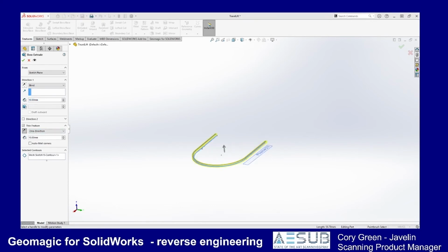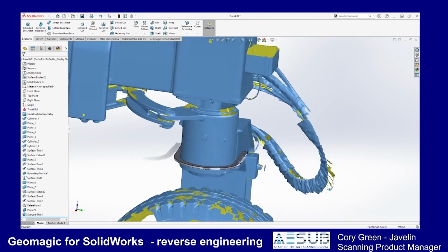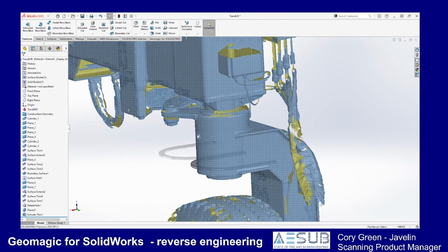Okay, we'll use SOLIDWORKS built-in thin extrusion feature. In this case, we can do a 30 millimeter wide strip around that horseshoe, and we'll assume that it's going to be cut out of 3/8 inch material. All right, let's see how that looks on the travel lift. Great.